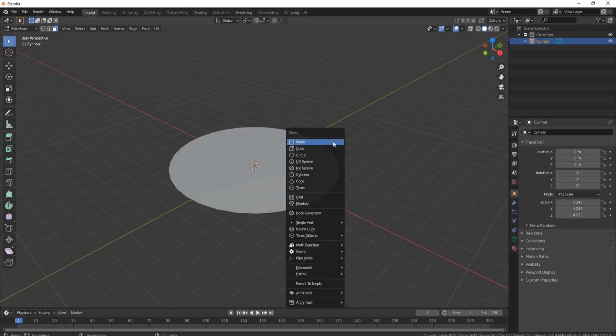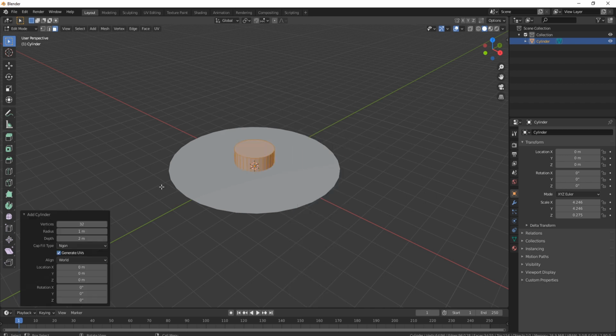So now let's press Shift A, and we're going to bring in another cylinder. Again, I'm going to leave this on 32, because I think that's about right for what I'm trying to do here. There's another reason I want to leave it on 32: I want to split this off into 4 pieces on every one, and the way I can do that is with 32 vertices. If I have it on 33 vertices or something like that, then when I try to bring them in or distribute them evenly, it's simply not going to work.